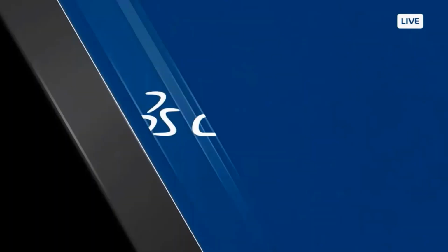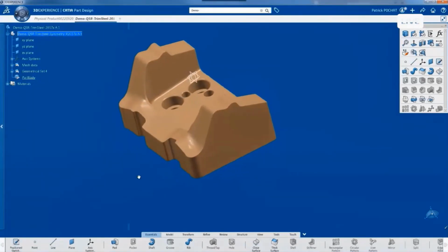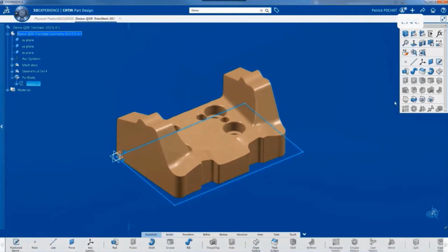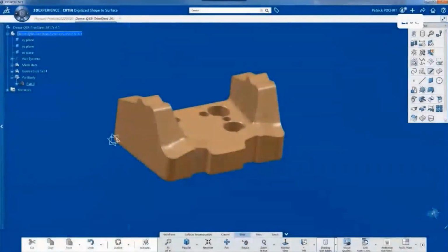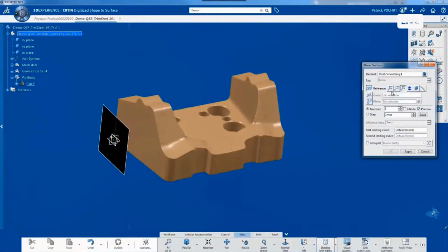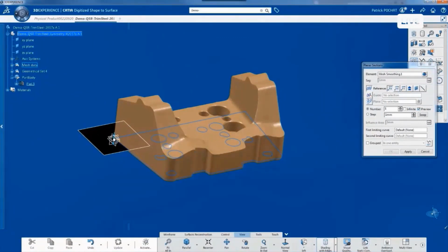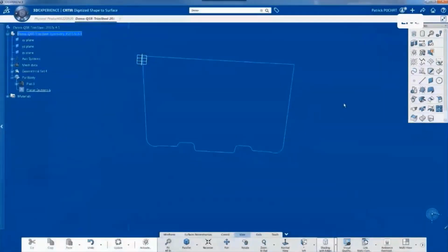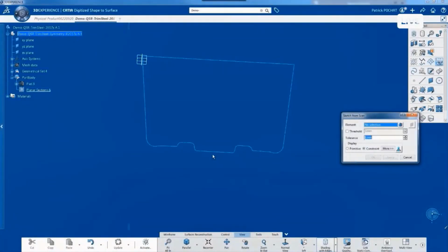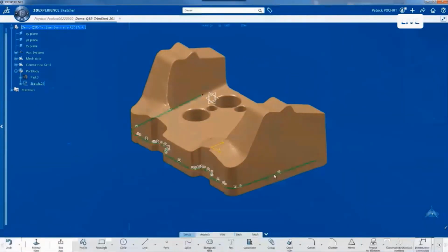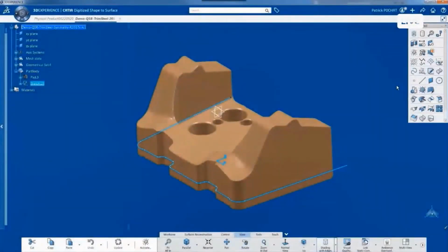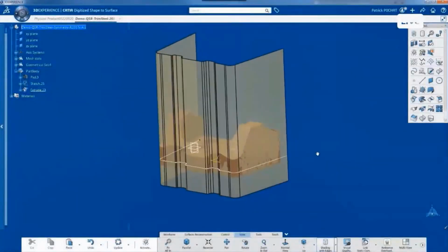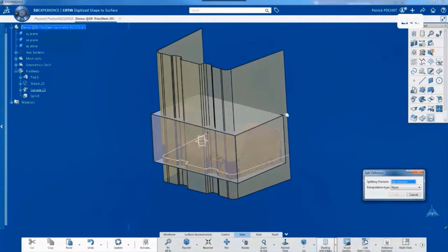For example, you scan the tool, you import in CATIA the STL file. Here, we will recreate a solid box exceeding the part size, and we will enrich the box little by little, like here, creating, for example, sections on the mesh, approximating later on this section into segments and arcs and ellipses. The result is a fully constrained sketch that you can edit and complete manually, like here, extrude it with standard extrusion functions, and refine the box you previously created.